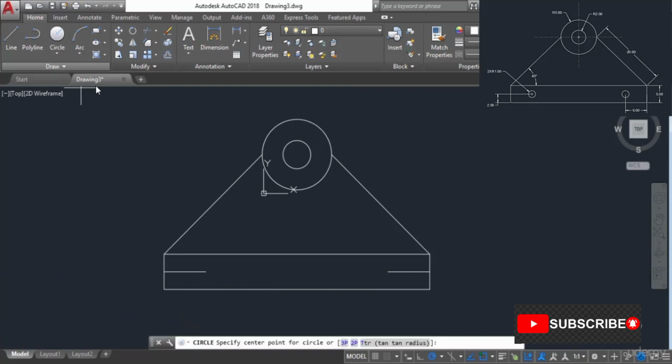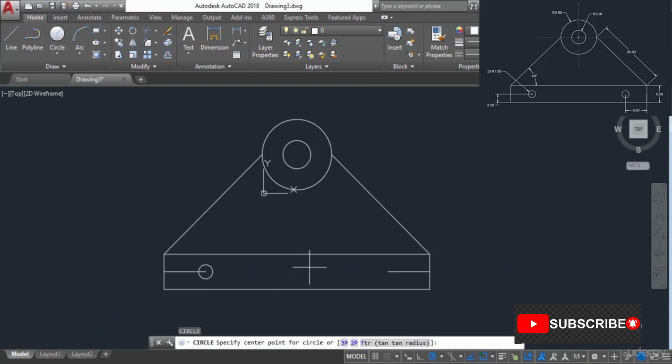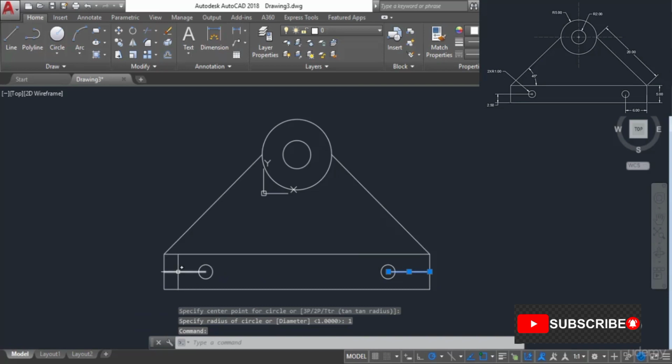Now go to the circle tool, click on this endpoint and make a circle with a radius of 1 unit. Press enter again, go to this point, make another circle with radius 1 and press enter. Now we can erase these two lines, these are no longer required. And there we have it, our final geometry as per requirement.